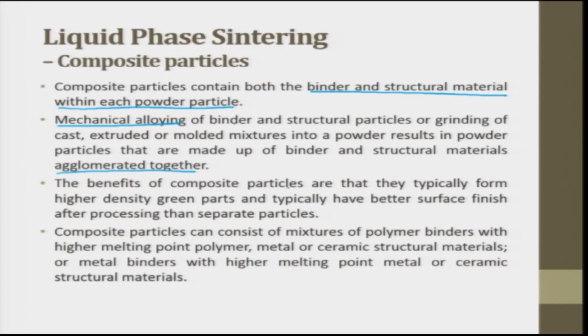The benefit of composite particles are that they typically form a higher density green part and typically have a better surface finish after processing than separate particles. The composite particles can consist of mixtures of polymer binders with high melting point polymer, metal or ceramic structural materials, or metal binders with higher melting point metals or ceramic structural materials. So, this is also important. What is that we are doing with each other?